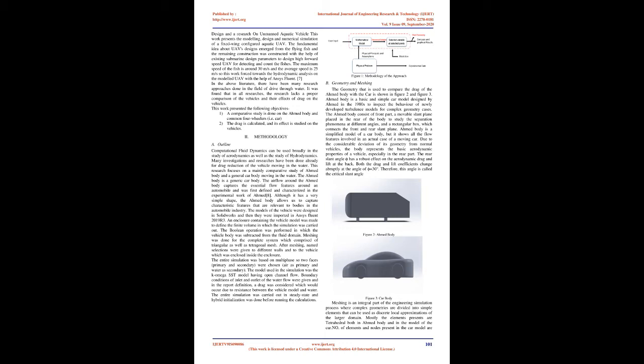5. Phillips et al. presented the use of computational fluid dynamics to assess the hull resistance of concept autonomous underwater vehicles. Three AUVs have been modeled in CFX to determine straight-line resistance. This has then been validated against existing experimental data. The ease with which shape and appendage modifications were made, as well as the inclusion of the free surface, demonstrates the success of the parametrization strategy and its suitability for considering concept hull forms.